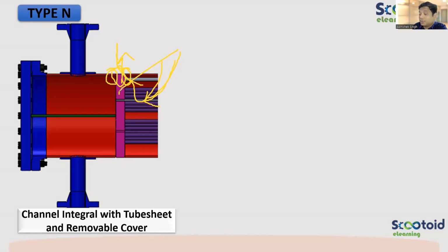So this is a glimpse of an application, and how it becomes the choice. There is not only one factor which affects it. You have to see multiple factors: how thermal performance is affected, whether it will be economical to make. Safety comes first, and there is no compromise on that. If you have a very hazardous fluid, you cannot compromise. Even if you don't have a way to clean it, you'll have to discard your vessel and make a new one, but you will not make a bolted joint just for cleaning. Getting it, guys?